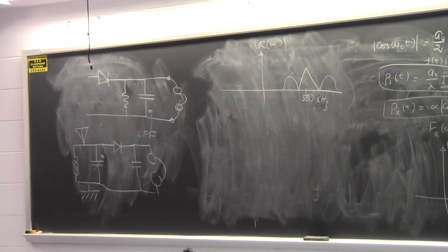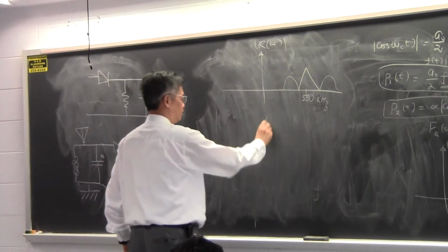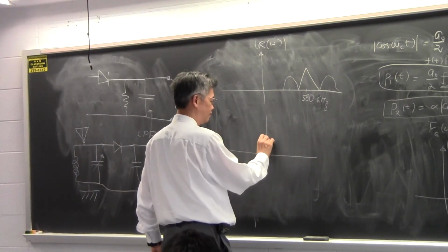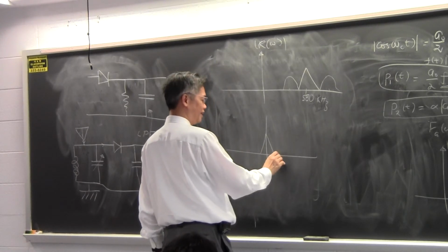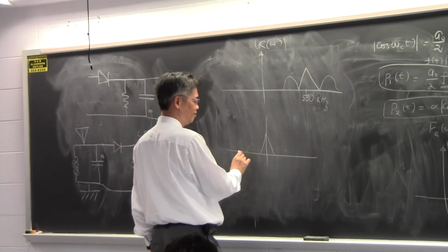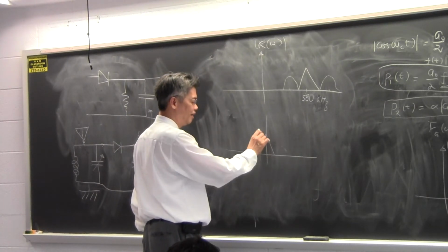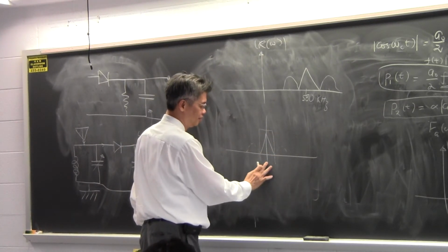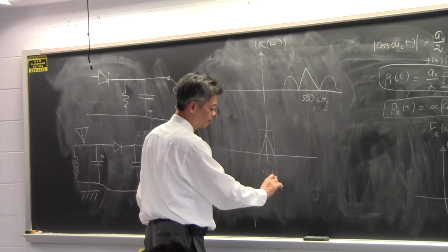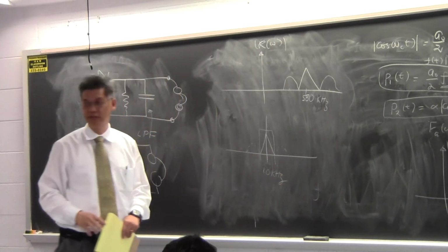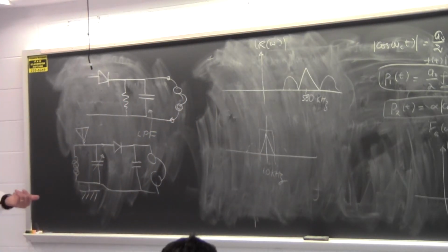So in order to pick up these stations correctly, after you do a coherent detection and bring it down here, you might get the other stations over here. And in order to pick up AM580, you will need a 10 kilohertz bandwidth filter in order to not pick up the other radio stations.